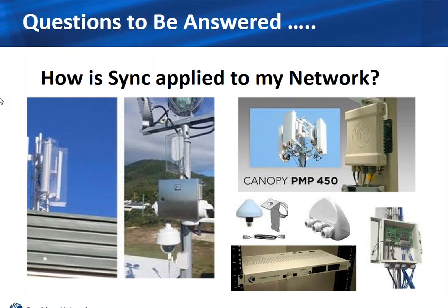But I believe that there is a setting that you can select which solution you want to utilize, whether it's timing coming from the PoE, timing coming from the external sync port, timing coming from the built-in GPS, as far as operating the unit. So it's basically within the radio configuration. I believe it's under general. There's different tabs on the access point, and under the first general configuration tab is the selection of how you want the GPS synchronization to work and where you want it to derive that signal.